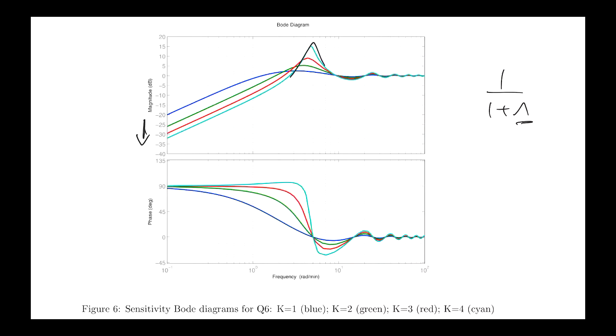That will typically give rise to more oscillations in the step responses of the closed loop system. Remember, a step input doesn't just have energy at 0 frequency, it has energy distributed across a range of low frequencies. In fact, it has energy at all frequencies; you get this sinc function. So a step change is going to have some energy at this frequency, and the peaking up here suggests that component of the step change will be amplified, and that causes the oscillations in the transient response.